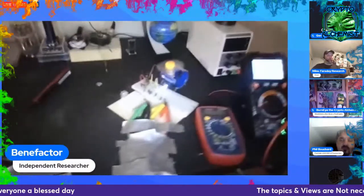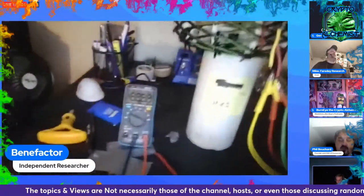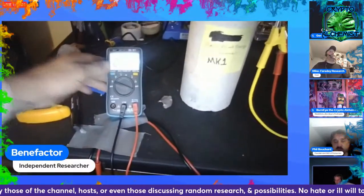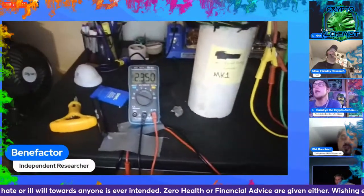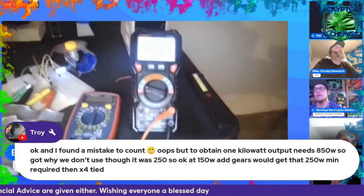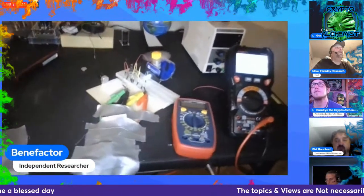Testing 1 2. And we're getting 3.6 volts on the output. Let's take a look at the input. Try slowing down the pulse rate. 2.3 volts on the input. Can you see that? Take off the light on it. Now we can see it. 2.350 on the input. That's voltage. And you got 3.638 on the output. Yep, there you go. And it's powering a load.